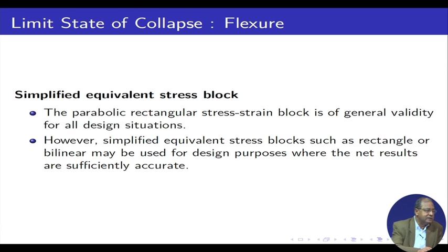Now we are telling something, though we are using the same stress block, but here the code says the parabolic rectangular stress strain block is of general validity for all design situations. That means, whatever we have done in IS 456, that is also applicable here.